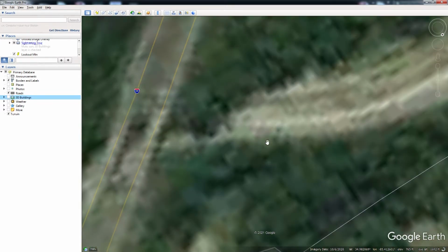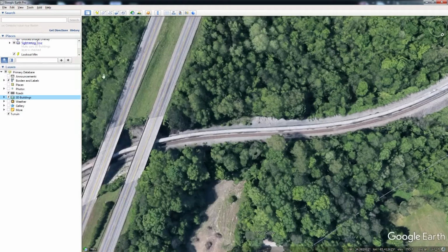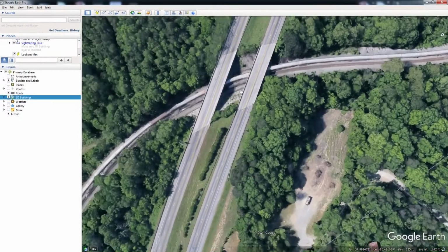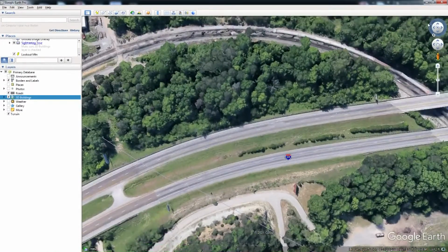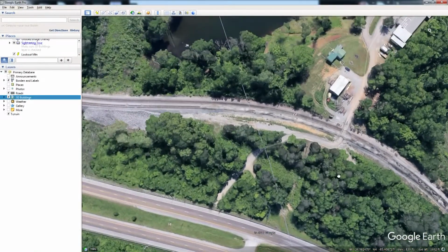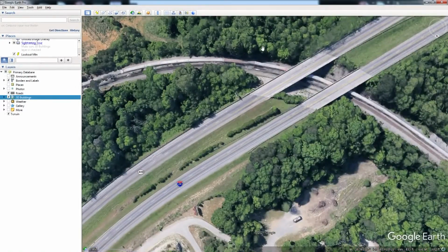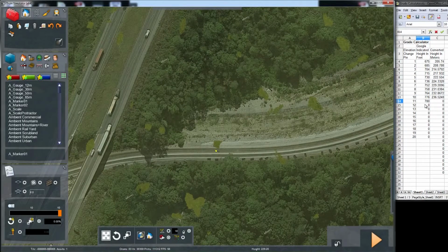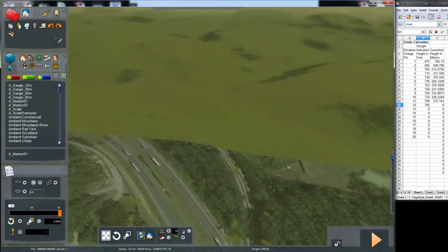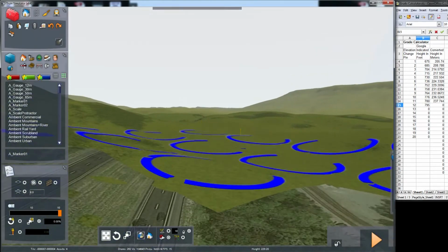Tick off 3D just for a moment there and see what that gives us. Yep. I'm going to call it 795. I actually like it in 3D mode because it makes the bridges appear the way they should appear. And we're going to make that our final pin for now. 795. Okay, so let's pull the track on from where we ended up to that point.